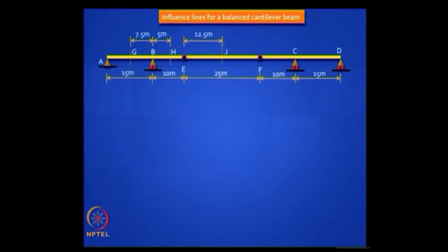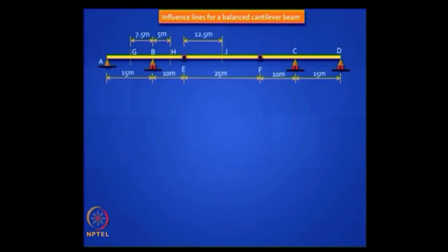So what you need to do is to find the influence line for MJ. What should you do? You put an internal hinge there and move it either up or down. If you move it up, then you will get positive values, which is what you should get for sagging moment. So you should follow a sign convention, but you can also try drawing and getting the support reaction at A and B. Can you try that? Influence line for support reaction at A and B and so on.